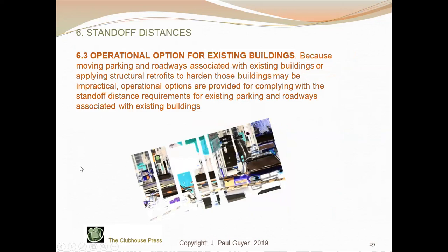Okay, this is worth commenting on: the operational option for existing buildings. Because of the impracticality of moving parking and roadways associated with existing buildings, or applying structural retrofits to harden those buildings may be impractical, operational options are provided for complying with the standoff distance requirements for existing parking and roadways associated with existing buildings.